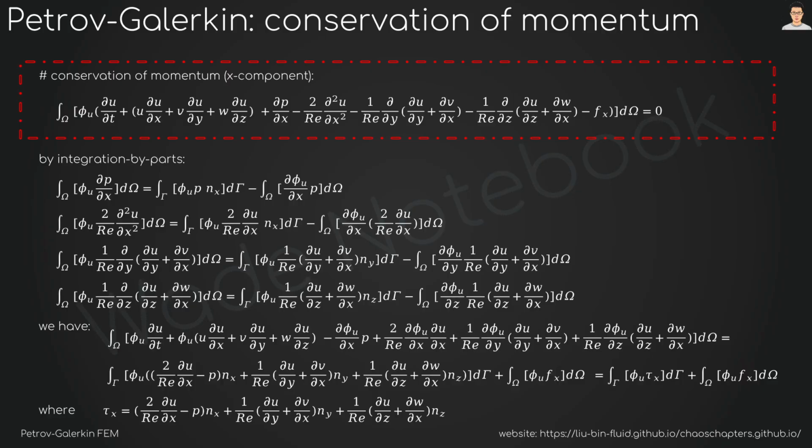In finite element syntax, we call these traction variables secondary variables. The secondary variables are different from the primary variables. The primary variables refer to what we are solving for in a weak formulation. This is why we usually see the Navier-Stokes equation in its primary variables, whereas the secondary variables are quantities derived from the primary variables through constitutive relations or differential operators. They are not solved directly and are usually computed after obtaining the primary variable field.